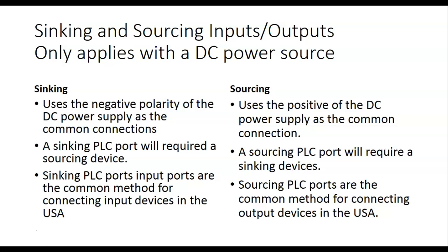Sourcing uses a positive DC power supply as the common connection. A sourcing PLC port will require a sinking device. Sourcing PLC ports are the most common over here in the US. So all the PLCs we have up here either are sourcing by default or we've wired them to source.